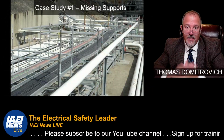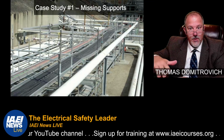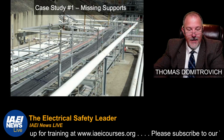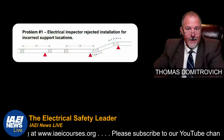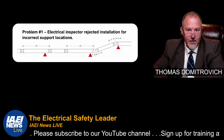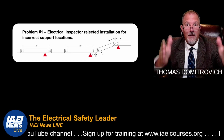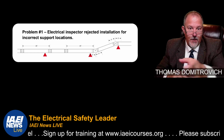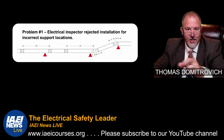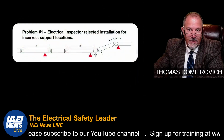All right, look at this. Missing supports. This is what can happen because of the weights. If you don't have the proper supports, you can get sagging of the cable tray, and I'll tell you, you see this, that is ungood. The electrical inspector rejected the installation for incorrect support locations. This is where they had the support locations, and you can remember what it says: no more than 2 splices or expansion joints between supports. And look at this one. There's the 20 foot. So there are 2 splices in between the expansion joints. That's where the sagging occurred, right in there. There are 2 expansion joints in there, or 2 splices.